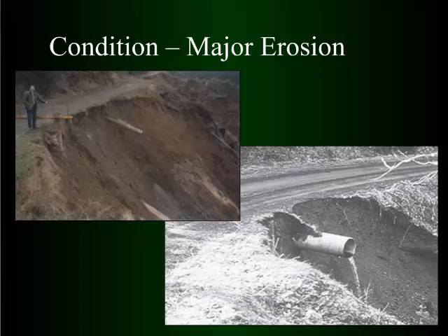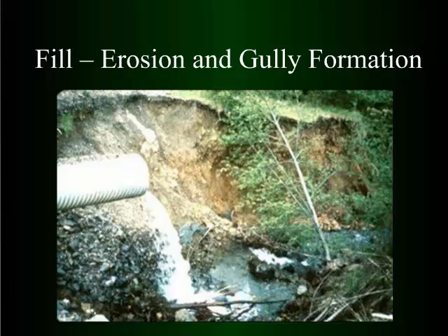This looks like it was a cross-drain pipe. Probably, I mean, it's a pretty good sized failure with that one. This one here might have been a stream since there's water coming out of it. It's failed. I'm sure with their shoulder right here, the pipe was too short. You have a long fill slope here that was dumping water onto it. It saturated it, eroded it.